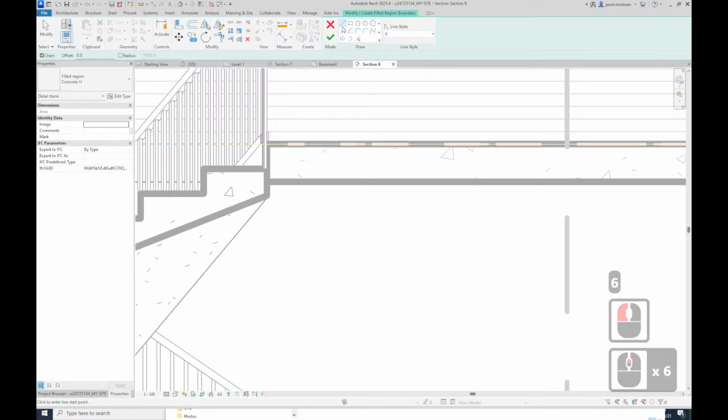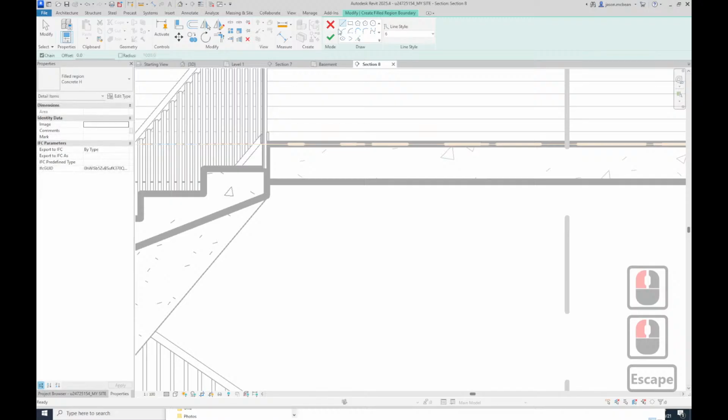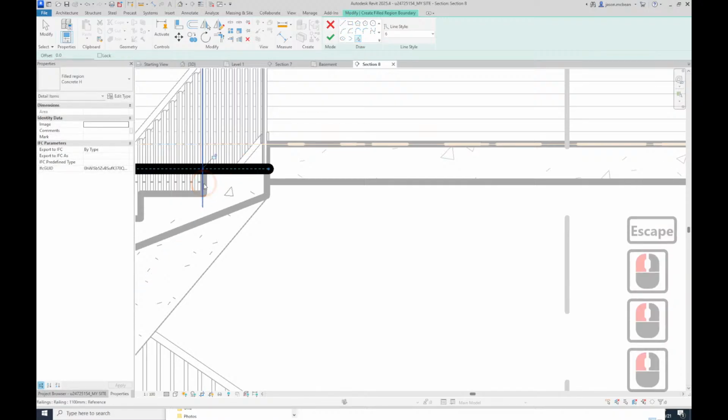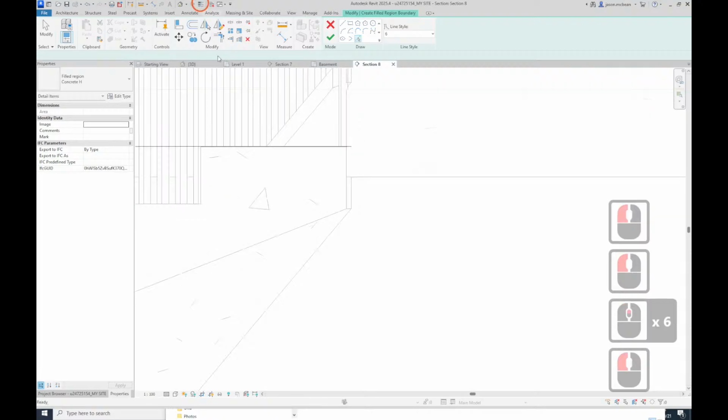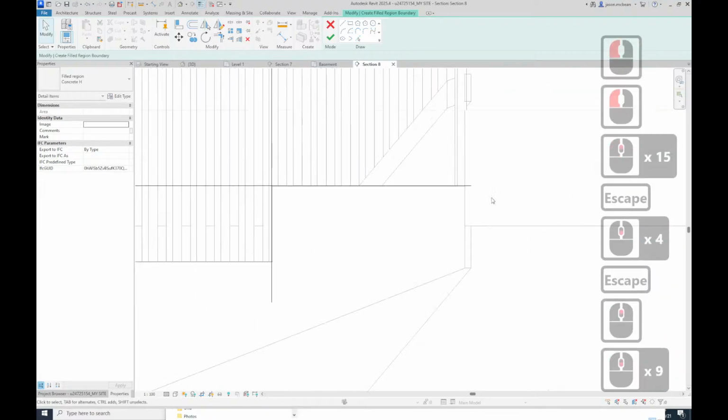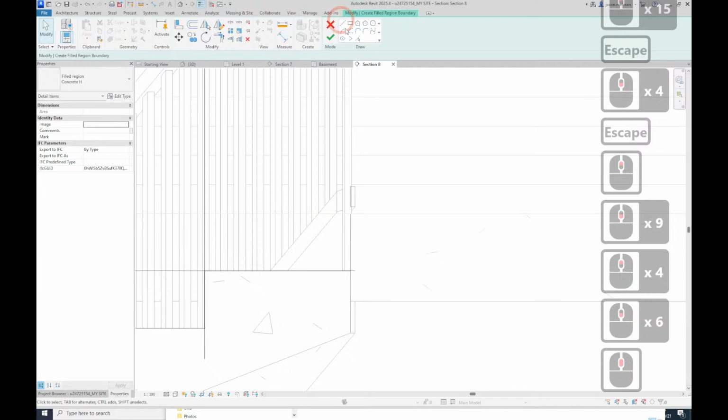So we're going to try our best now. Revit sometimes will pick a line, sometimes it won't. You know why? Because the stair's cutting at a weird angle. So here we're going to have to use a bit of luck. Revit and stairs sometimes are not very good friends, I've noticed, because it's doing a bunch of maths to try and create a stair.